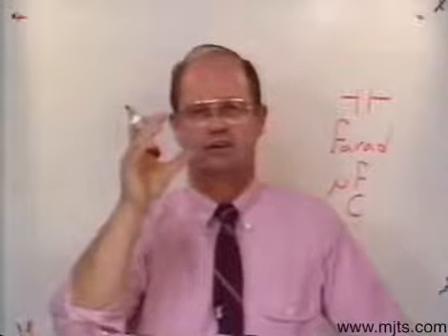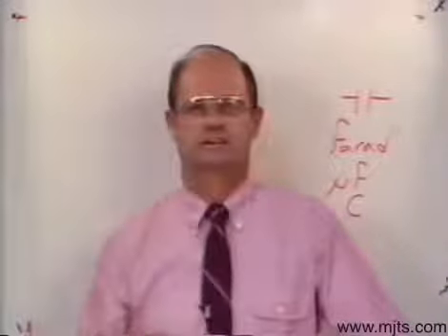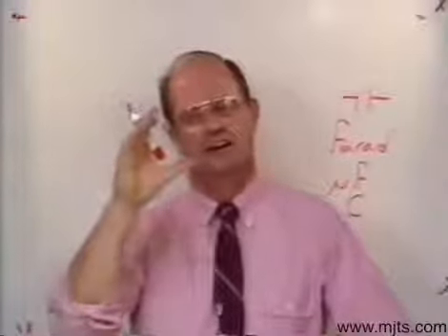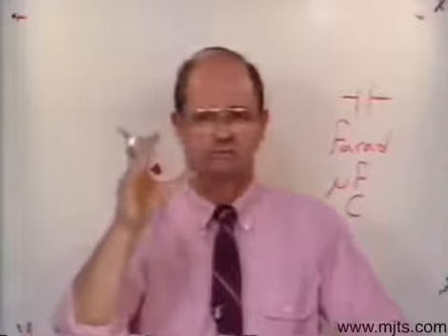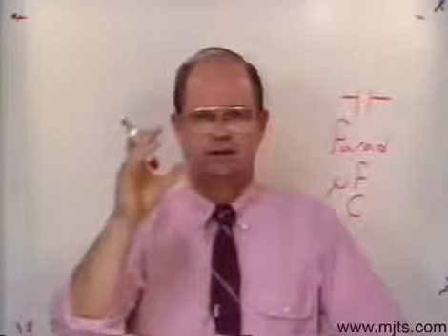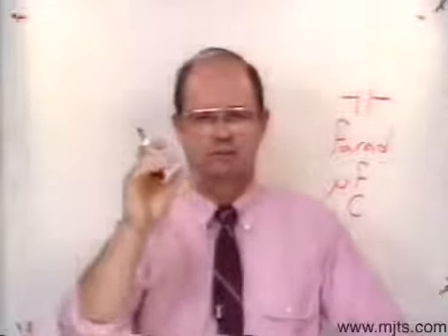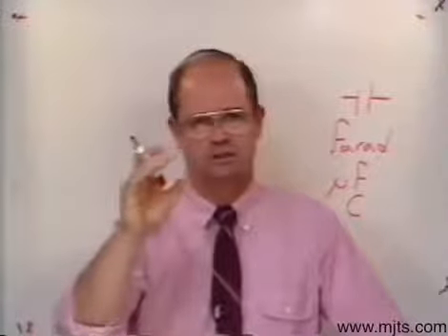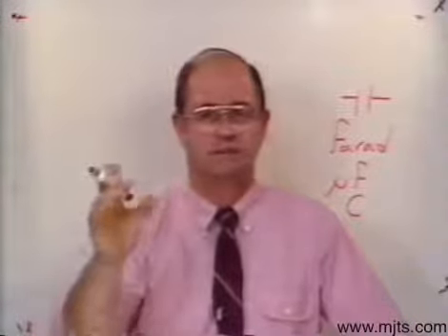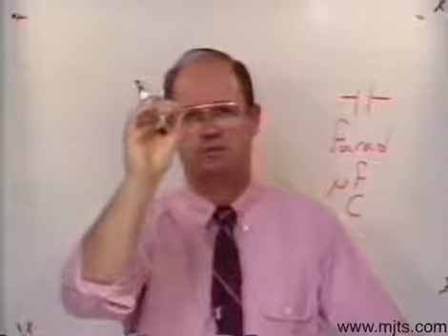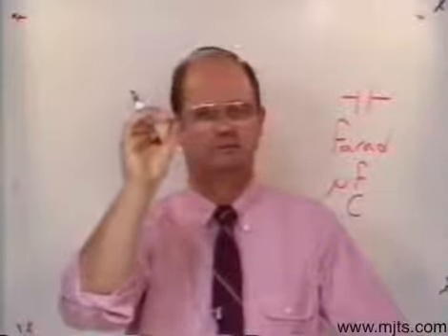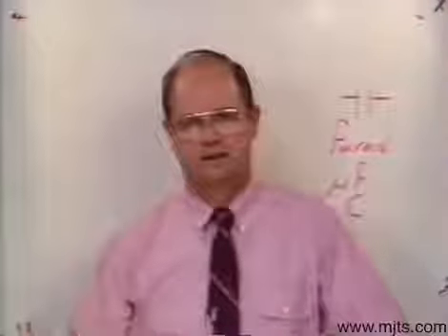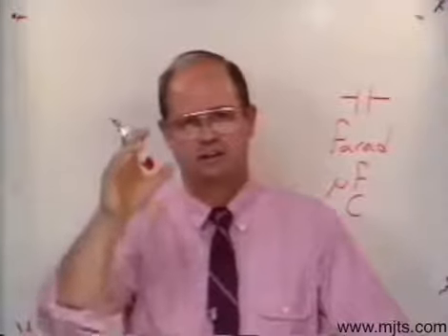If I was to give you an idea of about what a farad would be, you'd be talking about 1 farad as being, say, 2 plates that are probably 6.5 miles square, spaced out with air between them at 1 millimeter. Now, what is a farad? A farad is when a